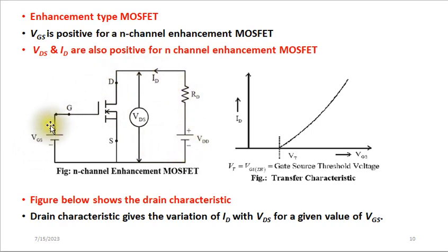So whenever this one keep on increasing, the concentration of electrons around the channel will be increasing, so that the concentration will reach our threshold value, so that it can create a physical channel that will connect the source and the drain by artificially creating that concentration ourselves using the VGS.